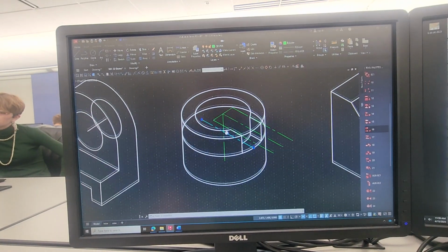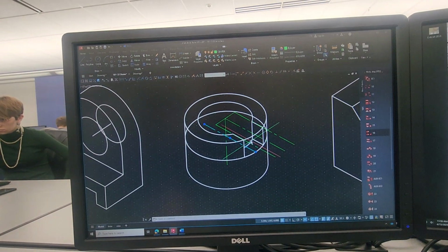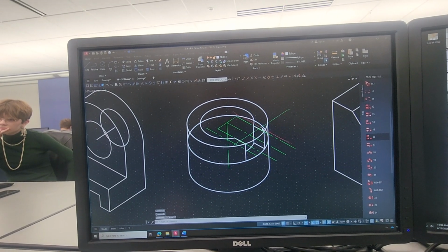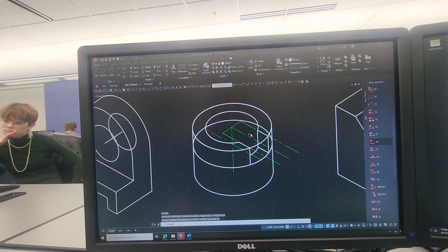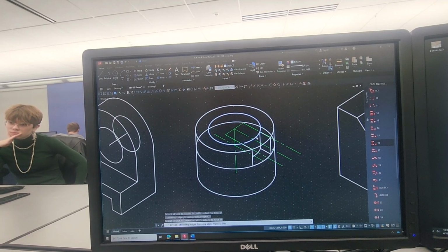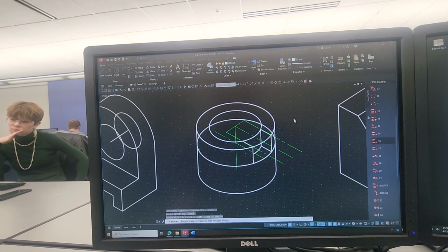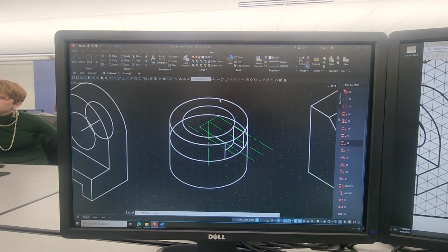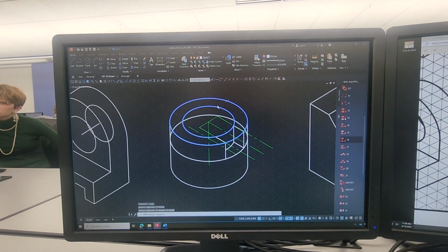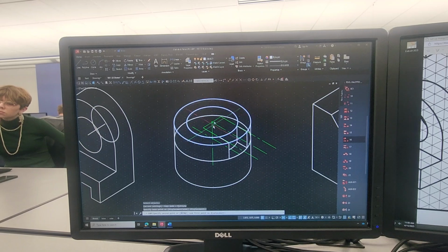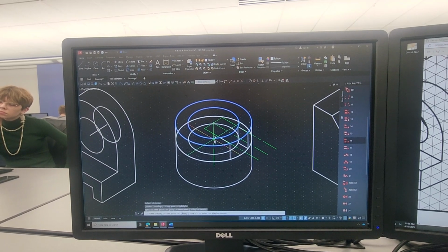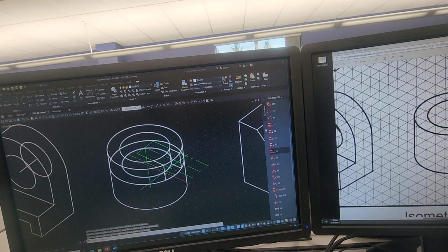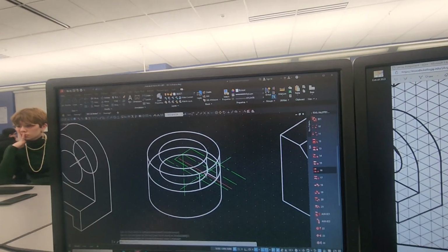And what I'm going to do is get these 2 circles, this guy and that guy right there. I want to make sure I extend this because I trimmed it out on my example right here. I'm going to extend that all the way to there and there. So I got the 2 circles, right? All I'm going to do is copy this circle and that circle on the top, take its base point right there, and then just go z down 1.5 units. You see what that did right there? Now this looks weird. People go, that can't possibly be right. It is. It just happens to be that little glimpse you're catching.